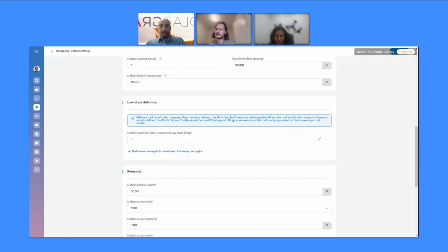In here, you'll see something called the power export limit. And some utilities will define a specific power export limit that may vary from home to home, tariff to tariff, and so on. If you don't want this system to ever export to the grid for whatever reason, perhaps you're trying to grandfather someone onto NEM 2.0, you can simply enter 0 here.